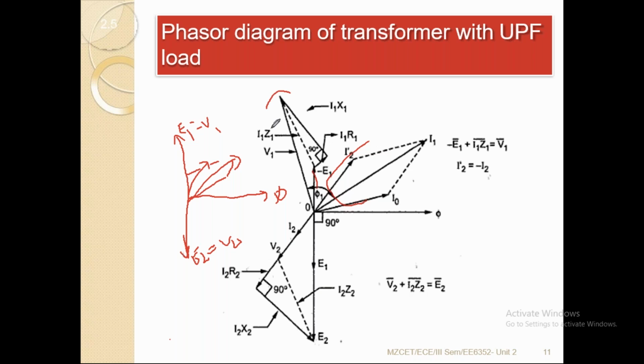Now additionally we are getting this part, and this part is due to the resistance load. So if you are getting this load, then you can form a right angle triangle with an angle of 90 degrees. Now if you have the right angle triangle, see here. In that the base represents the resistance and the opposite side represents the reactance.